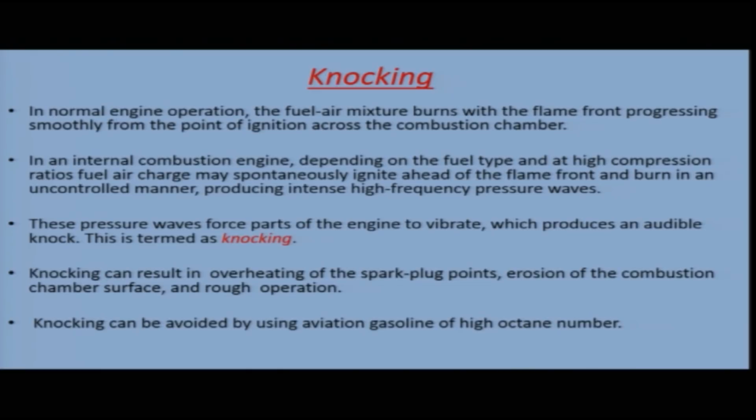Now, in an internal combustion engine, depending on the fuel type and at high compression ratios, in case the fuel type is of a different type or your engine is of a very high compression ratio, then the fuel air charge may burn spontaneously ahead of the flame front. So, just ahead of the flame front, the fuel may burn spontaneously and in an uncontrolled manner. So, in normal operation, the fuel was burning smoothly and the flame front was progressing smoothly from the point of ignition.